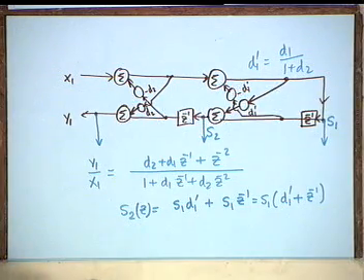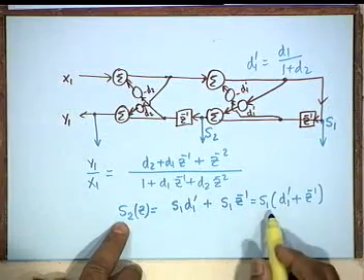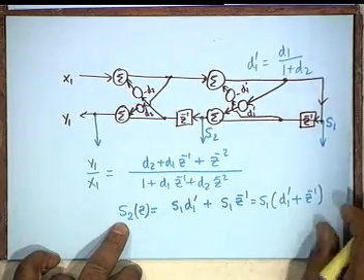This is a very elegant contribution to DSP literature, that an all pass lattice can be used to realize any arbitrary IIR transfer function, and you will see how things fit into place. Okay. So, we have established a relationship between S2 and S1. Let us find out what is S1.